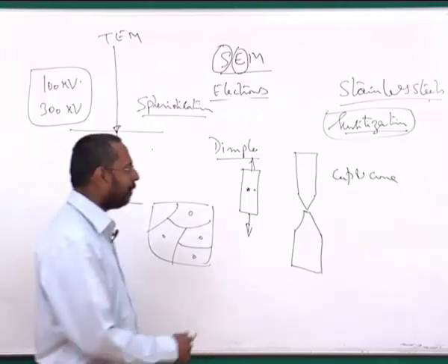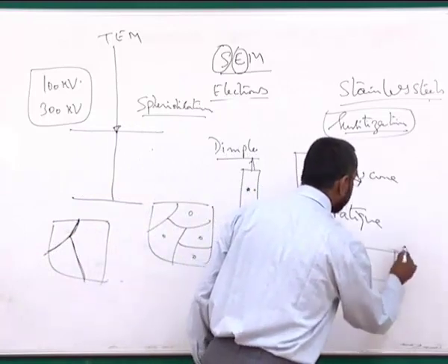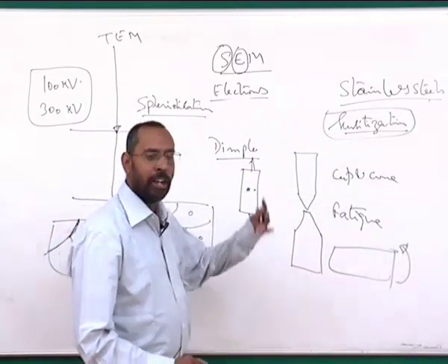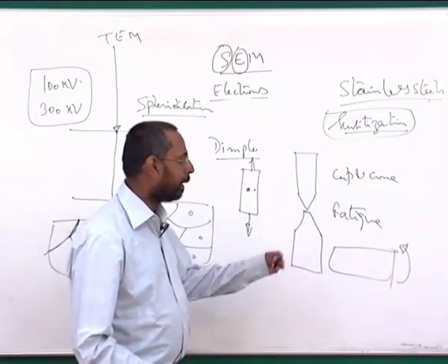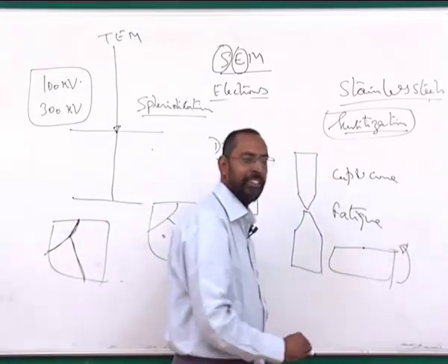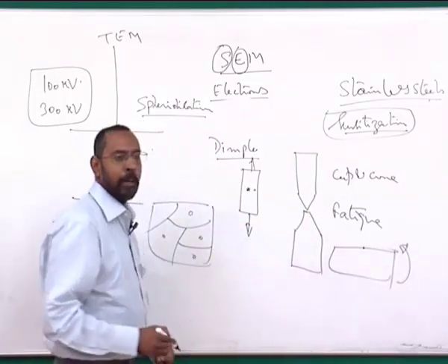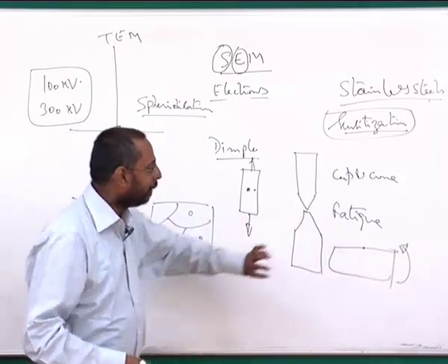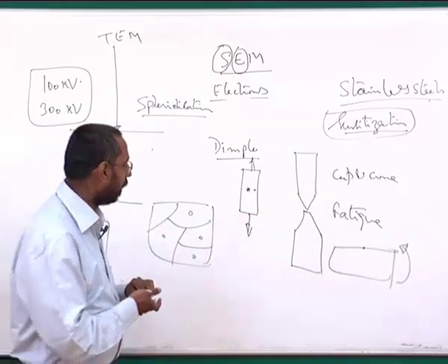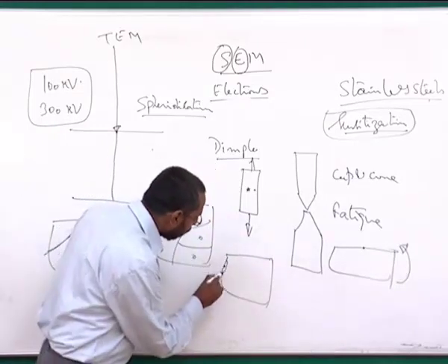Similarly, if you have a fatigue fracture, usually, if you take a crankshaft which is rotating, as a result you have both tension and compression forces alternately being exposed by this material, and usually the cracks initiate on the surface and start forming and then propagating. Because the cracks propagate with this tension and compression loads continuously being experienced by the material, you would see, when it fractures, wherever the crack is starting, certain ripples.